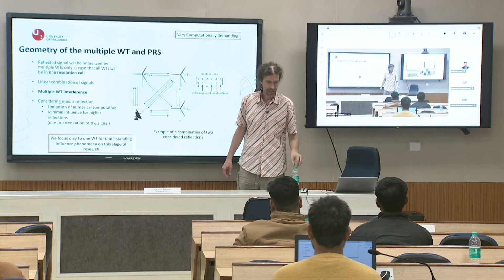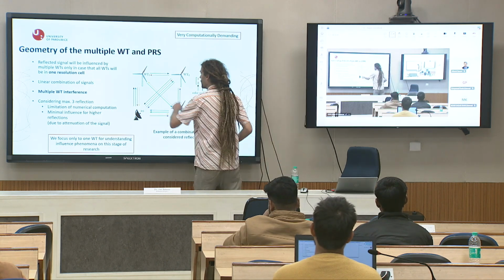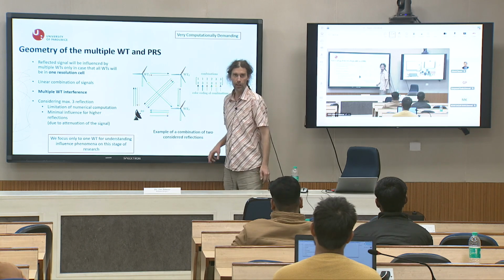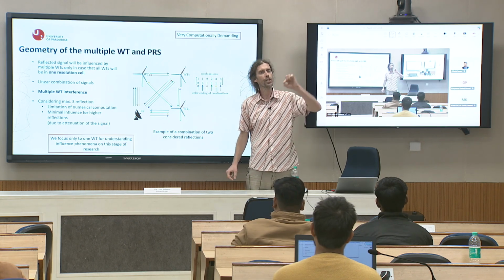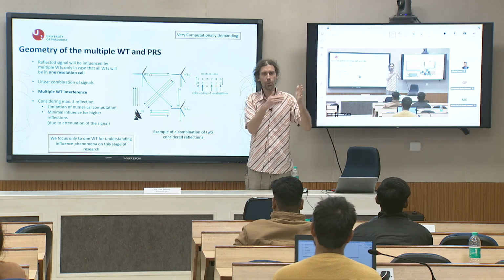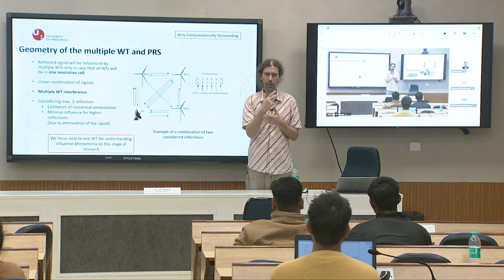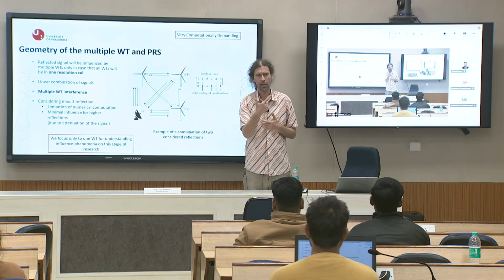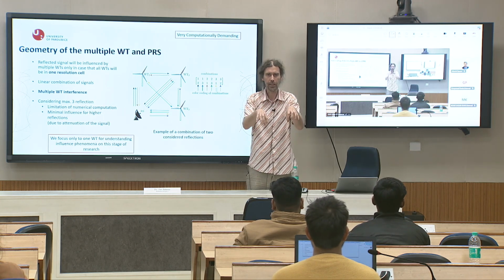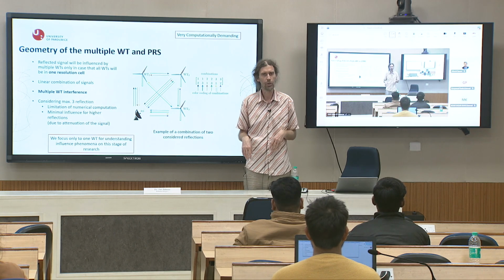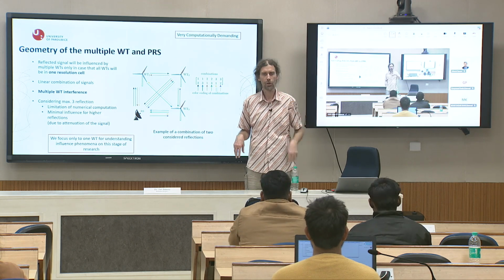We discovered the dependency between 2, 3, 4, 5 reflections, because of course there can be multiple reflections and then go to the radar. Forget it, it is too complex, and with each reflection the signal is more attenuated. So we just discovered that the maximum is 3 reflections, but better 2 reflections. But again, only in one resolution cell. If it is separate in each resolution cell, forget it. You can behave with this simulator as if in each resolution cell there is only one turbine.